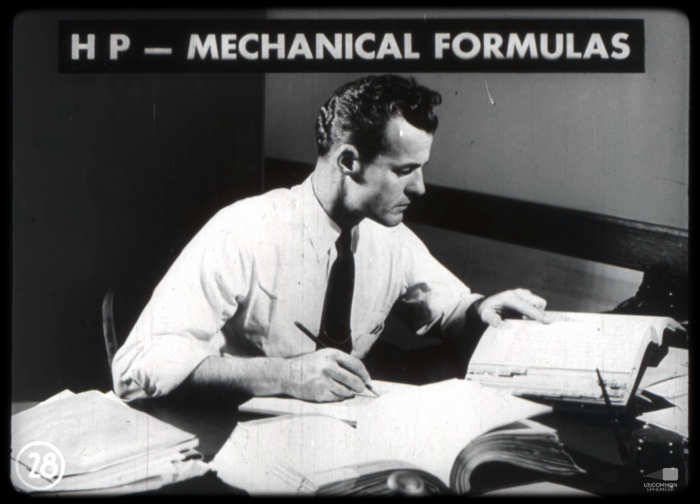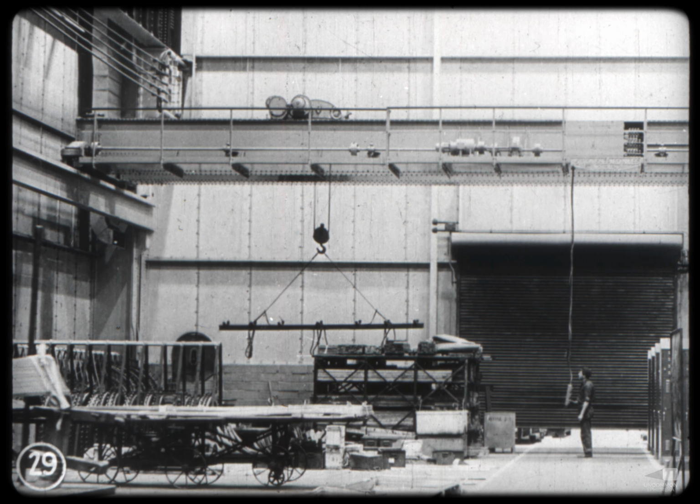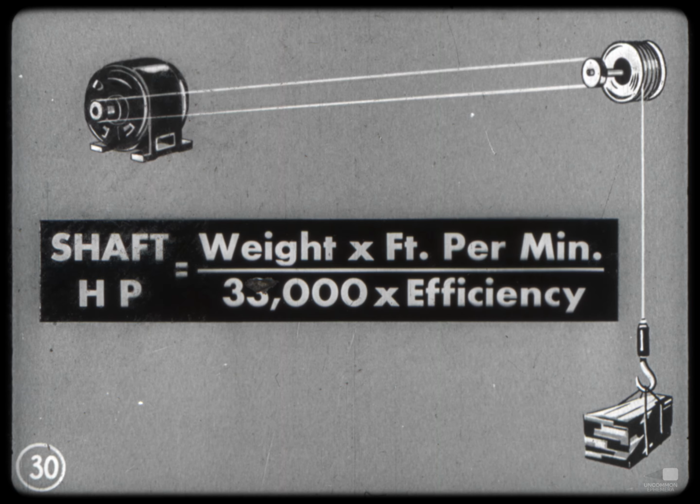One method is by well-known mechanical formulas found in engineering handbooks or in any text on mechanics. With a hoist, for instance, if the weight of the load is known, the speed of hoisting, and the mechanical efficiency from the load to the motor shaft, then through mechanical formulas, the motor horsepower needed at the shaft to hoist the load can be determined.